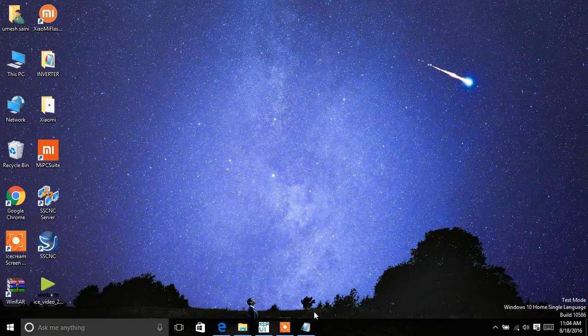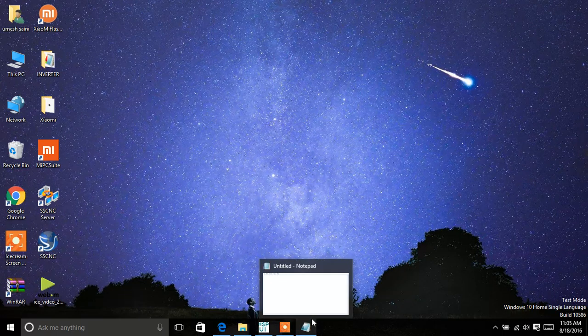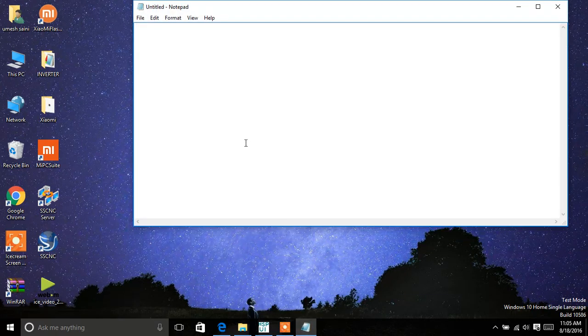This video is all about the transient analysis of a CMOS inverter on the tool HSPICE. In this we have to define a netlist of the circuit. First of all we have to write down the SPICE netlist. We have to open the notepad.